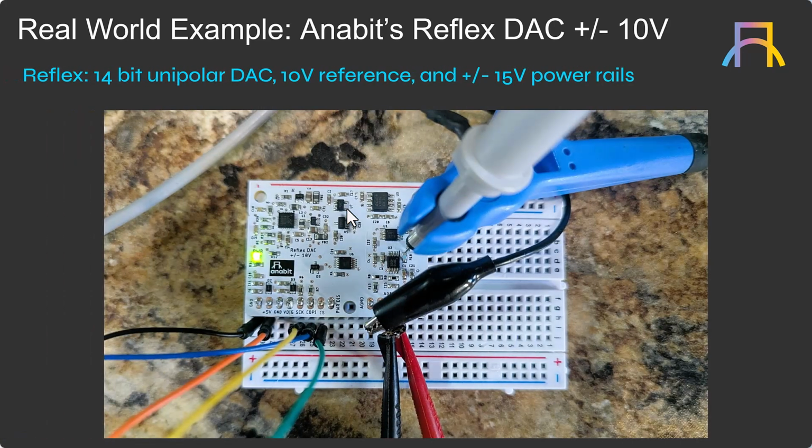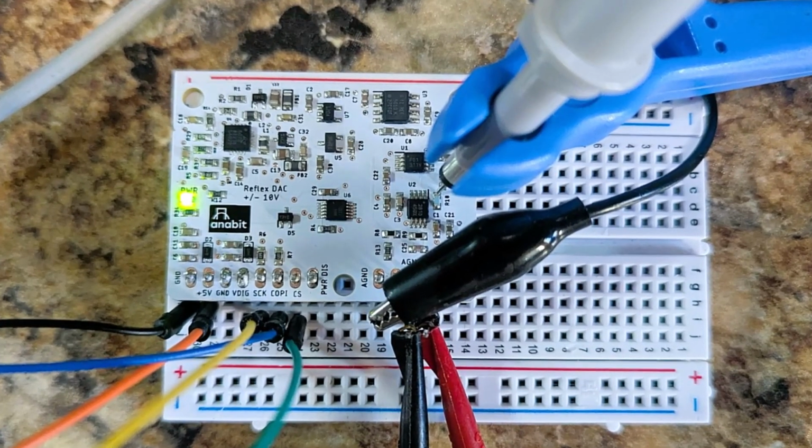Here's an image where I zoomed in a little more on the Reflex DAC so you can see a real circuit implementation of this. Here is my DAC IC that's creating a 0 to 10 volt analog signal. This is my 10 volt reference, high accuracy 10 volt reference signal. Then this is a 2-channel op amp. So it has the buffer amp as well as the summing amp there. You can see the oscilloscope tip is right on that R1 resistor that I showed from the schematic, or the output of the buffer amp.